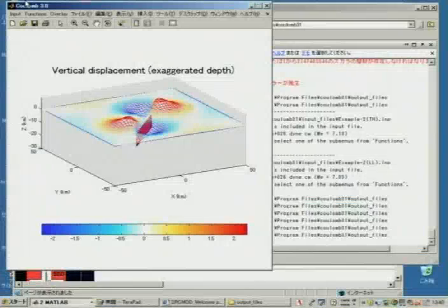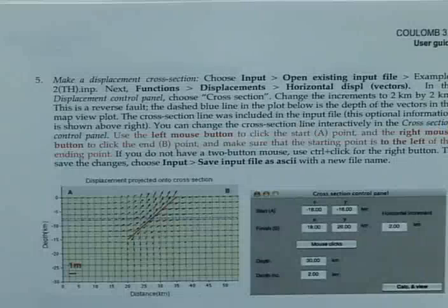So what you'll do is go to page 28. You'll see a little piece of a numerical file there, which is the format we're using for GPS data. Very simple: long, lat, and the easting, northing, and upward direction, or if you like, the east displacement, north displacement, and vertical displacement. And we're showing you how you can do that in Excel and get it into Coulomb. And Shinji, do you have the Nagata file?